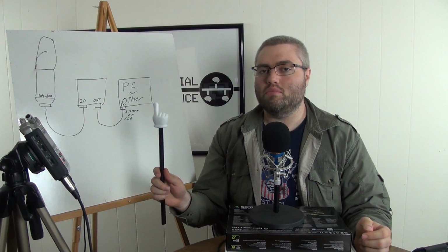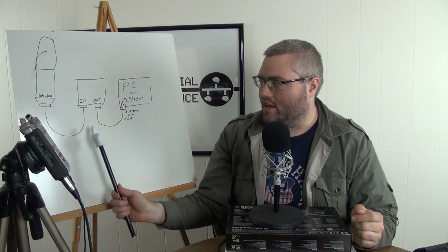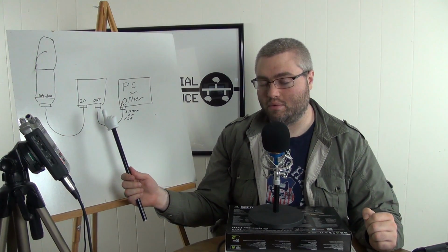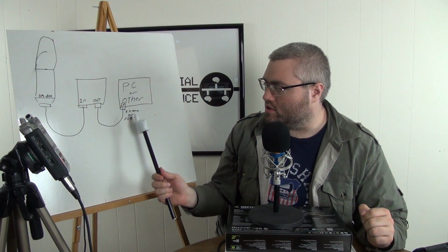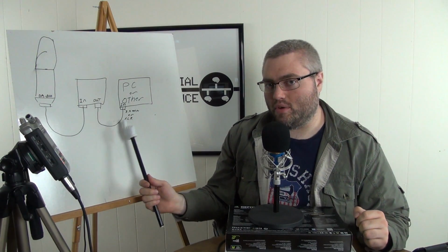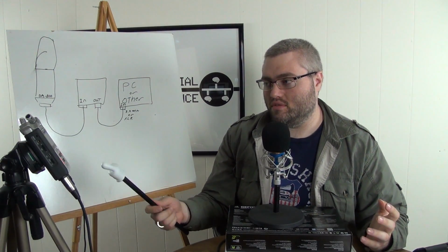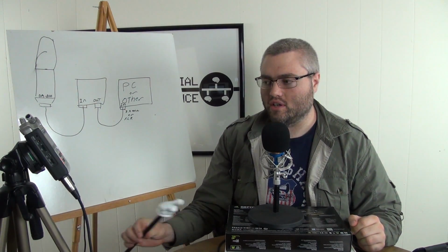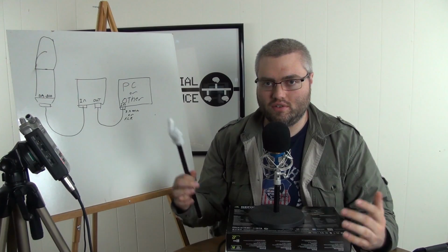This is how to set it up. Plug one end of the XLR cable into the condenser microphone, the other end into the in port on the power source. Take the other XLR cable, plug it into the out on the power source, and into your PC or other recording device. And this is the cable that would be the XLR to 3.5 millimeter jack, or if you have something like a Zoom, as I have here, then all you will need is just one XLR cable into the Zoom. And with the Zoom, it provides the phantom power, so you don't need a power supply with it.